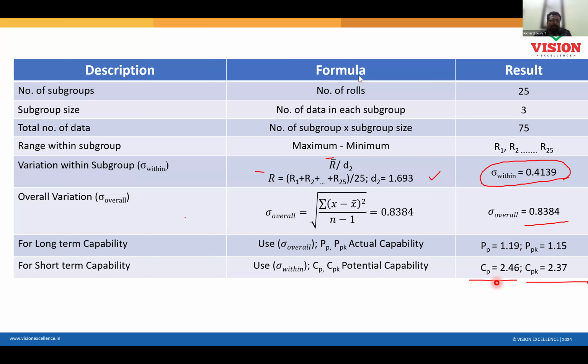Pp, Ppk. You must. So at least you get a better estimate of the capability. If you are the auditor and you have to assess the capability in one go, yes, necessarily you must look at Pp and Ppk. All of you understand? And when you are going for the audit and you want to assess the Ppk in one go, how will you perform the audit? Will you just refer to the report already prepared by the supplier, or would you like to collect the samples yourself?